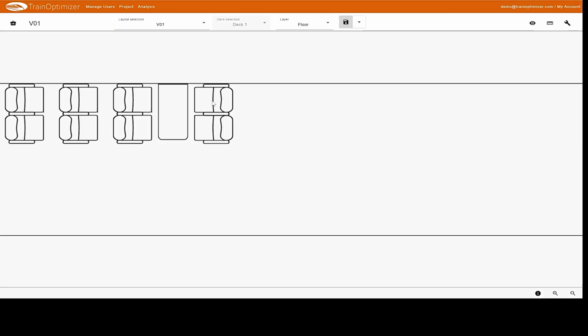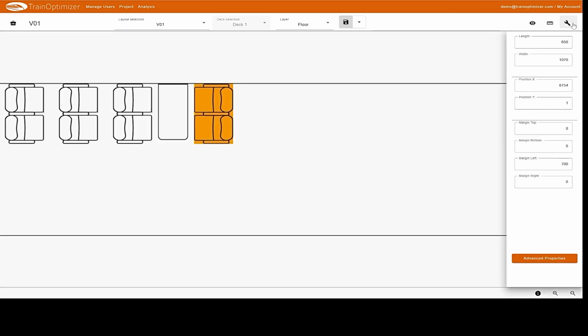To do this, we can either select a seat, copy it and adjust the spacing again, or we can select another seat that already has this spacing. We copy this. Right-click twice to change the direction, and the spacing is already applied.